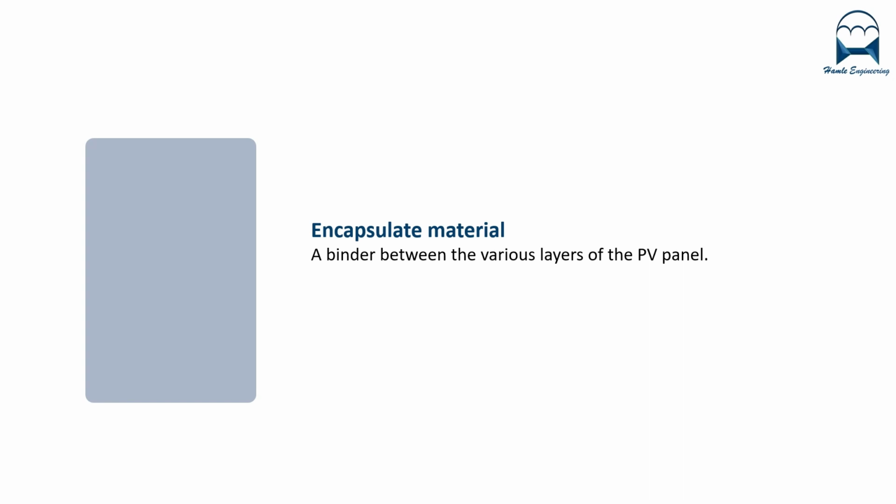When subjected to a thermal process of vacuum cooking, this particular polymer becomes similar to a transparent gel and incorporates the photovoltaic cells. The quality of this process, called lamination, ensures a high service life to the module itself, while the encapsulant quality affects the light transmission, the process speed, and the resistance to yellowing due to UV rays.